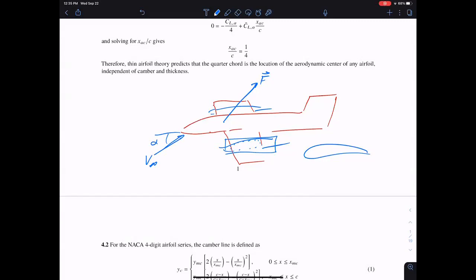The Reynolds number, how quickly are we flying? So that would be Reynolds number, the velocity, the density, the viscosity of the air. It also depends on our flaps. So if we have, let's say, a horizontal tail back here and it's got an elevator deflected, right? So it depends on that. It depends on maybe if we have our flaps sticking out, then that's going to affect the force on this aircraft. And so basically we're just trying to figure out, how do we predict the force on some aircraft while it's flying through the air?